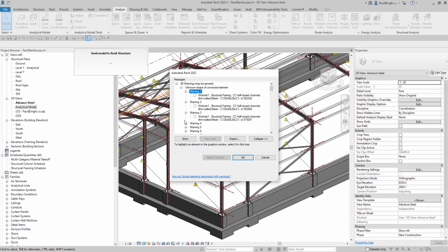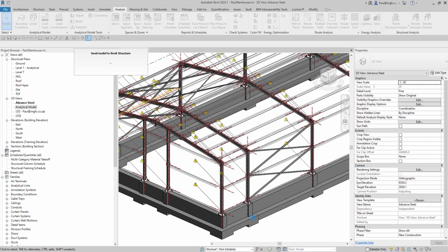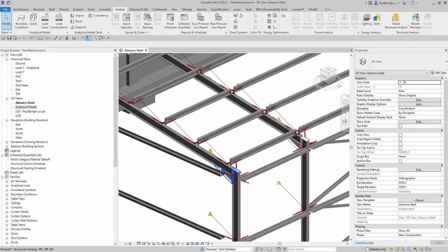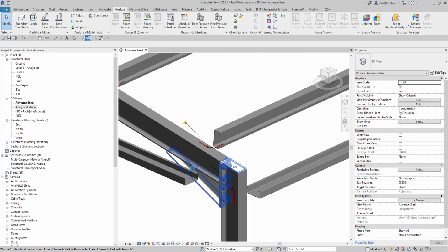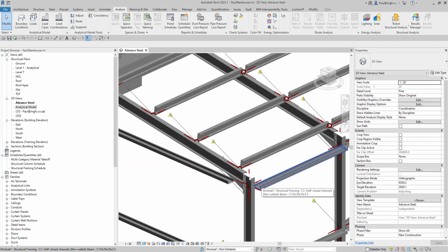Alright, so I would suggest that you start early with the process, or maybe create a parallel model for you to work between Revit and Robot, and Revit and Advanced Steel. Because Advanced Steel is of course a detailing platform, and it can read these connections very easily and update with those element properties.